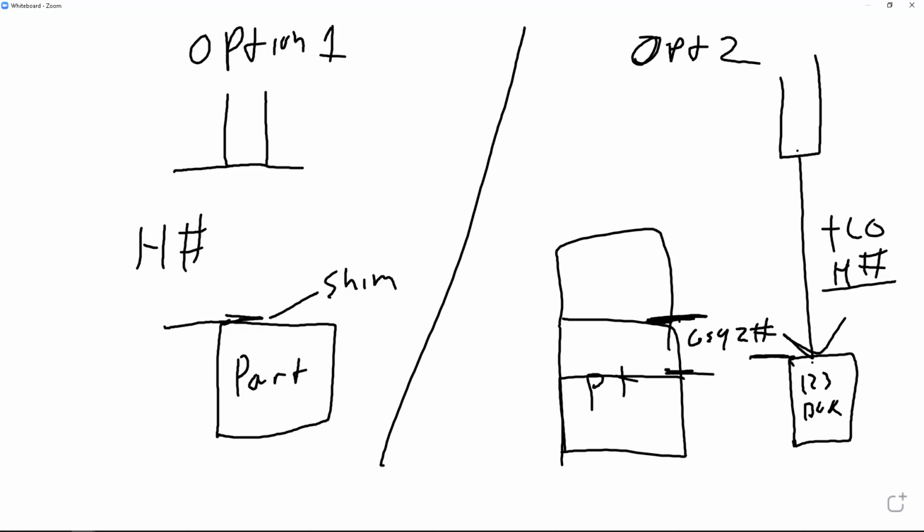We'll do that first. Then the second way is best if you're the only one operating the machine and you're doing different parts but have the same group of tools, all your tools already loaded. That way you only have to touch off once. So you have multiple part heights. You don't have to touch off all the tools every single time, and it saves you a ton of time.